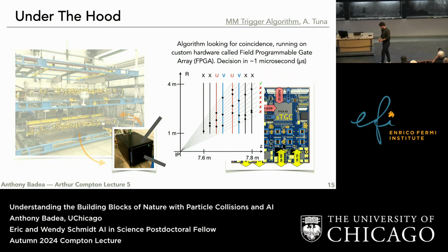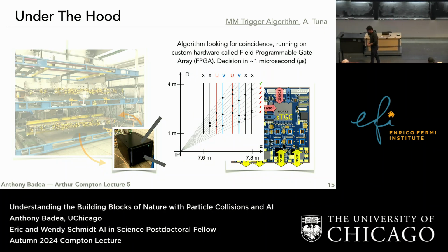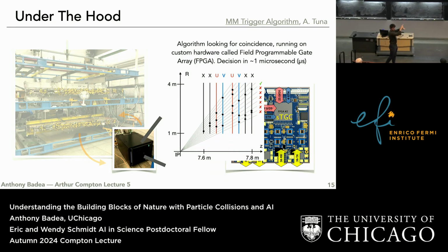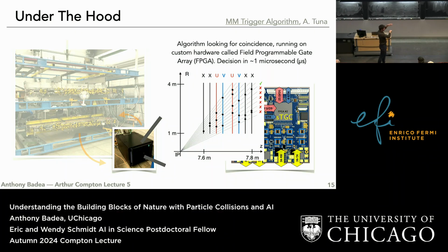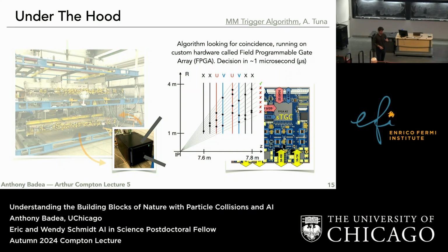How much it is, like this breakdown of electric field, we weren't seeing so much. What we were seeing was that electrical charge can leave noise hits, and so what we had to do is calibrate the electronics to set a higher threshold for an electrical pulse when it comes in for it to actually trigger a signal. So if you have a bunch of background noise, it can create a small pulse, and if you set your trigger level down here, then you'll actually care about it. But if you set your trigger level up here, then you won't care about it. So we did calibrations to try to get away from a lot of this noise. But the exact things that you're talking about, maybe you'll have to explain to me more afterwards. Maybe I'm not fully understanding.